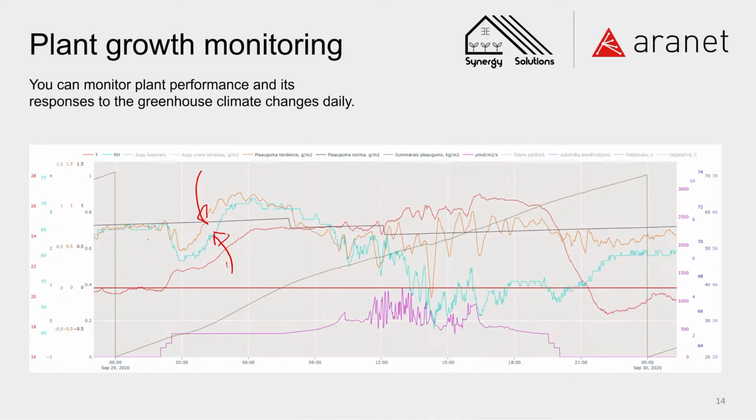So we see the corresponding changes in relative humidity are also changing the biomass growth trend, which you see also if this line is the biomass gain itself, then you see at what moment it switches and when it slows down and when it speeds up. So we are able to calculate which is the best temperature for the given plant weight for growing, and whether the rate of change of humidity will change our growth. And we see that if we have fluctuations in relative humidity or humidity in general in the greenhouse, we will see also quite some fluctuations of the biomass gain itself, where those changes are caused by natural light.